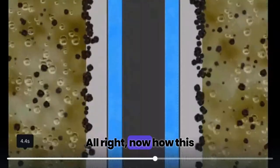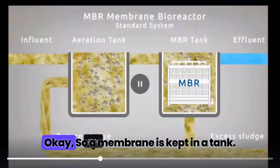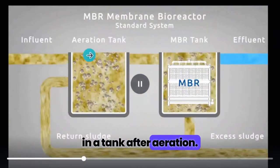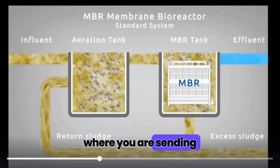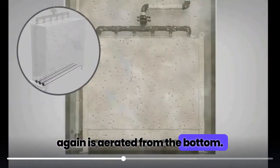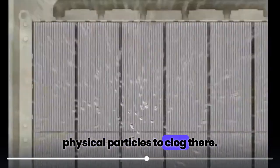All right. Now, how does this membrane work? We'll just go back in the video a little bit. Okay. So a membrane is kept in a tank. Please understand this. A membrane is kept in a tank after aeration. The tank is called the MBR tank, where you are sending biologically treated water. Right. This biologically treated water again is aerated from the bottom. The submerged membrane needs a little bit more air because we don't want those physical particles to clog there.